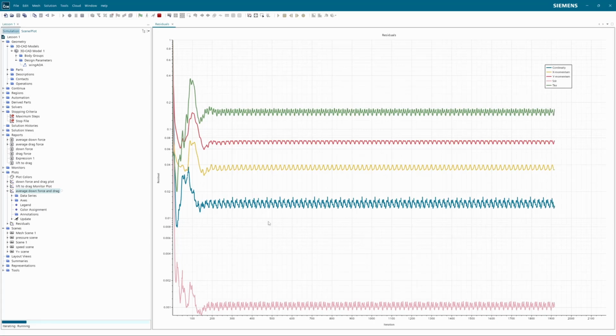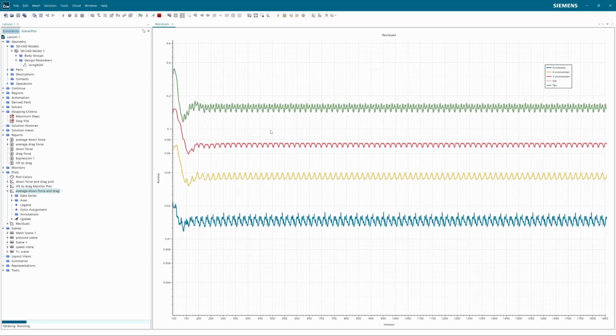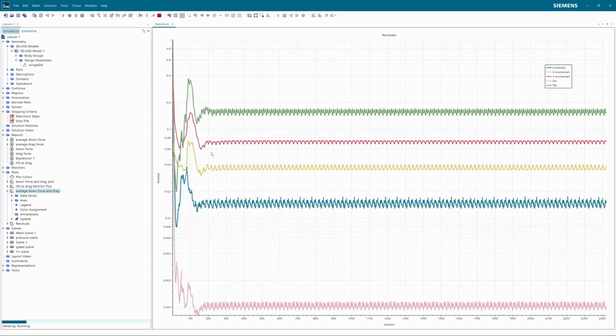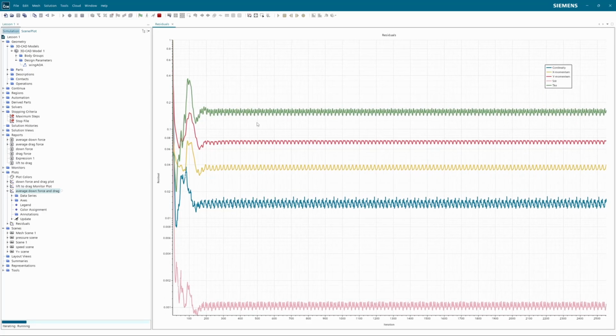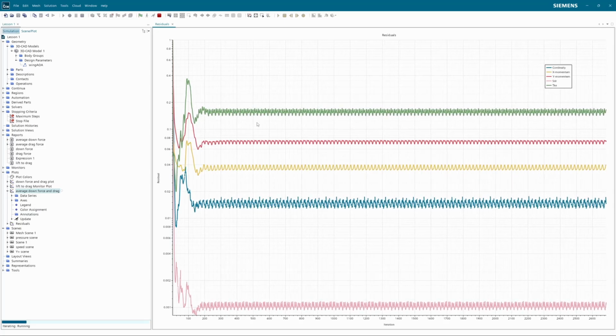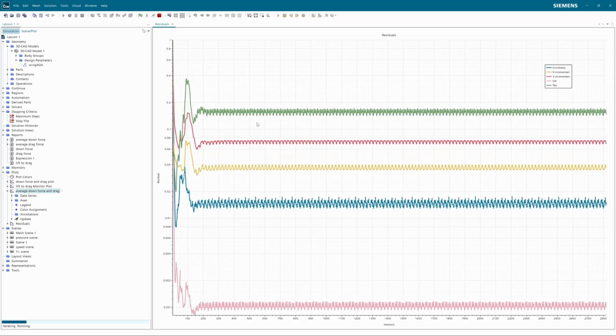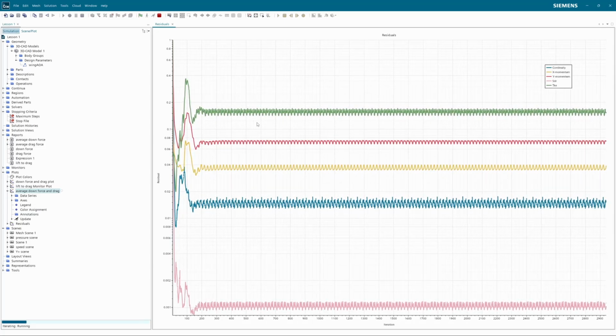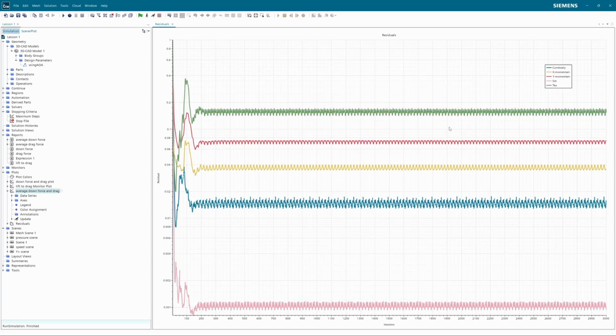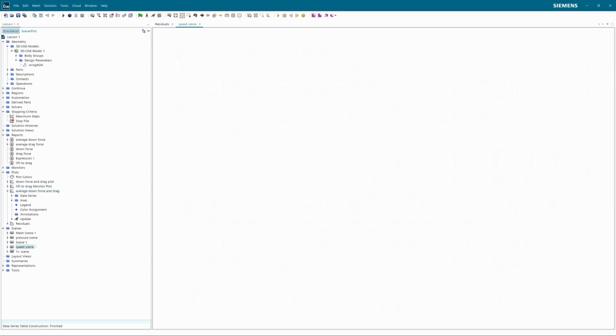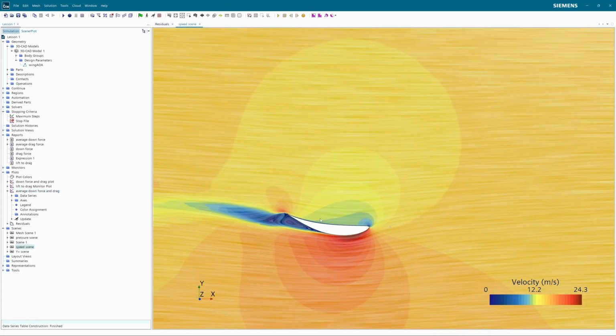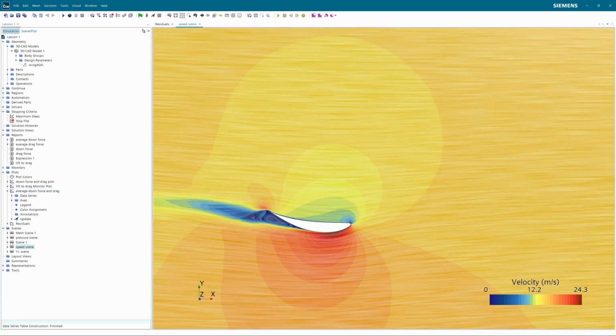So we will be really done in no time now, and then we can check at the end what the values are. Now it can still be useful when you're doing some new things to have a one-to-one view of what you're doing and to see if the flow is going correctly. If you're getting weird residual values, then you can check what might be going on in the speed scene and in the pressure scene.